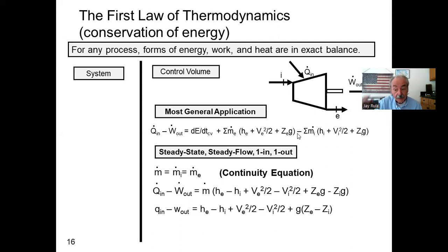Dr. Jones expected us to know that in our heads. I'll have to admit that as an undergraduate, I didn't have that in my head. Okay. Steady state, steady flow. I had that in my head. Okay. Remember, the sum of the m dot ins equals the sum of the m dot outs for steady state, steady flow. One inlet and one outlet, there's only one m dot. Okay. For one inlet, one outlet, steady state, steady flow, open system.